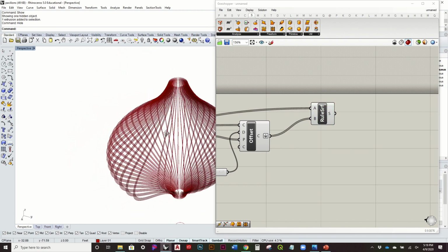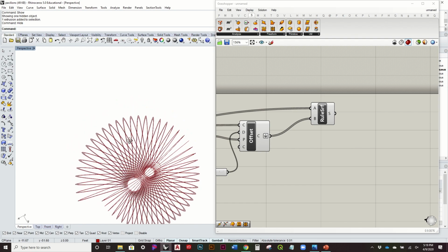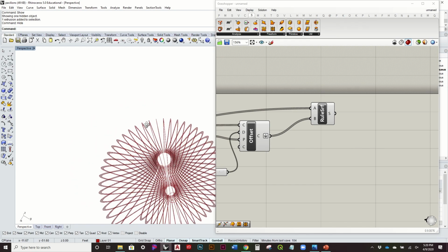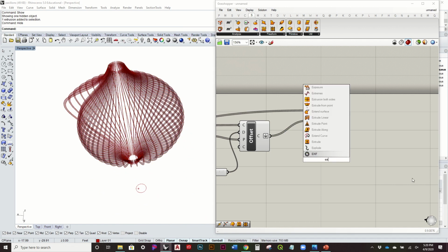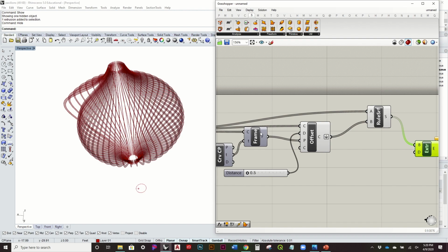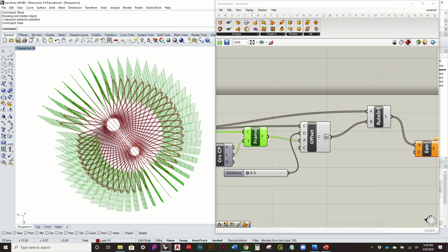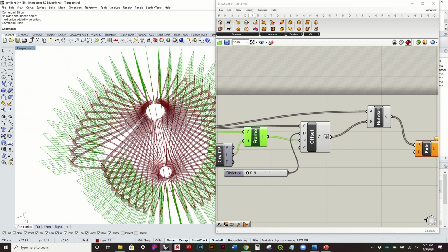But you can see now we've got an actual surface, but again, it's just an undefined thickness, so we want to extrude those. So I'm going to do extrude. And again, this is what's important, because we want to make sure that we use a specific direction. So that's what, again, our horizontal frame is. So if I turn that on, using this frame, we want to use the z-axis to give it that thickness.